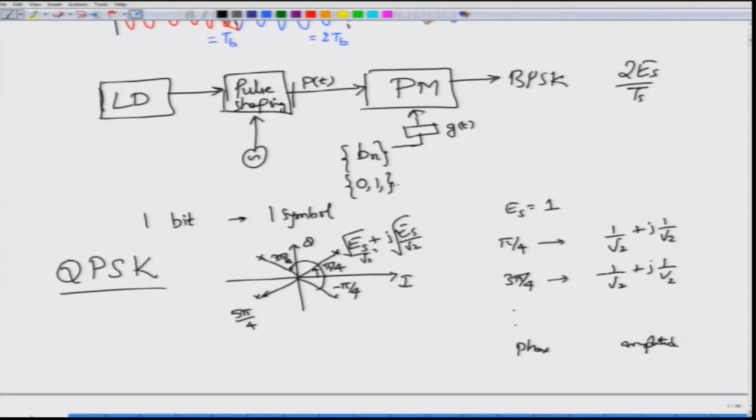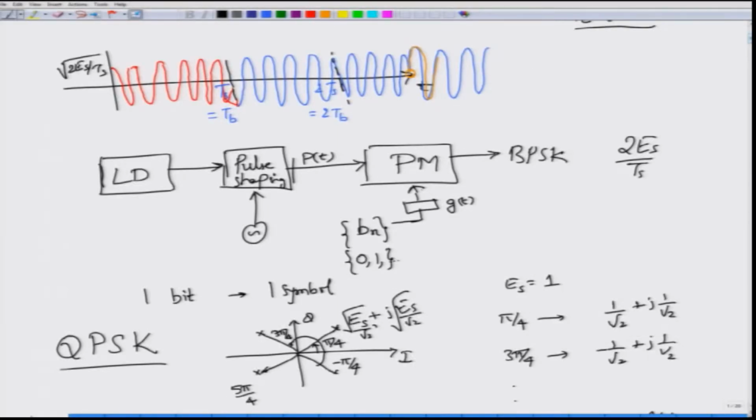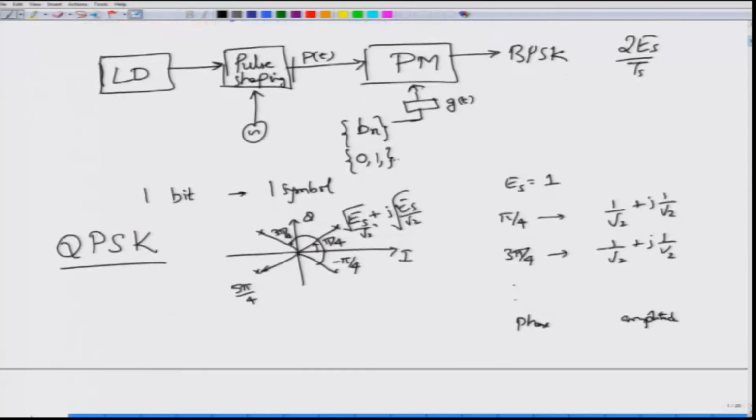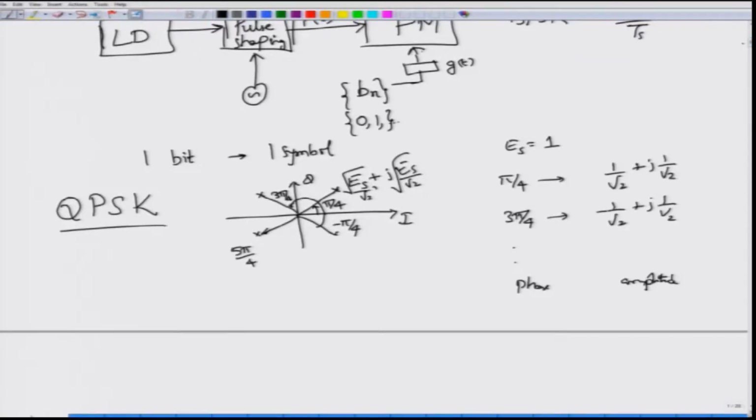However, there is one thing that we have not yet done. Remember, in the BPSK modulation that we had taken, we had a bit or a symbol, or rather if you go back to the constellation, you had constellation points, which are simply some numbers in the IQ space, and they had to be mapped into the corresponding symbols. For BPSK, symbol is equal to bit. In this particular case, you have 4 such constellation points, and you can map these 4 constellation points to 2 bits per constellation point, correct.